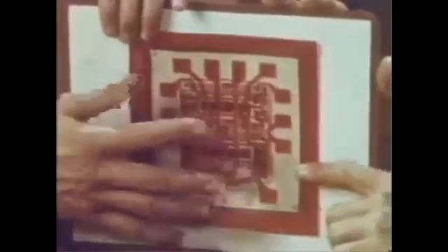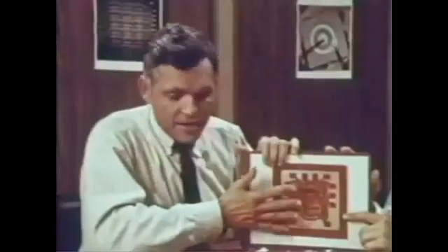Now, the artwork which I showed was only one mask, potentially. Here is the artwork in reduced plastic overlay version, which goes with a complete set to make an integrated circuit. There are 5 to 7 or even more of these potential masks. All of these must align carefully and precisely. These will then be translated into another set of glass masks, which will then be used for contact printing directly onto silicon wafers. In working with silicon, this is what you begin with: a silicon ingot.